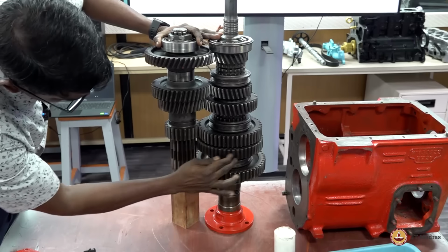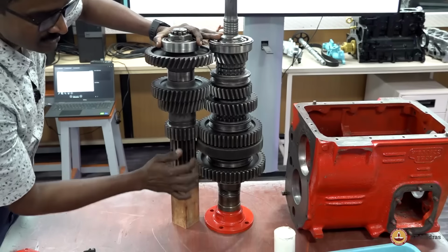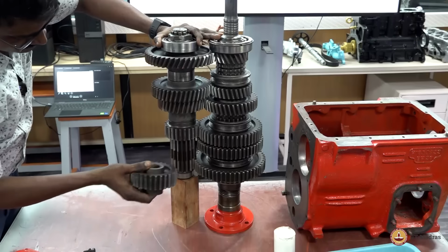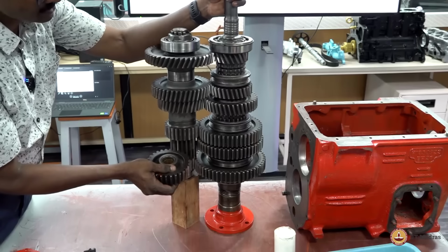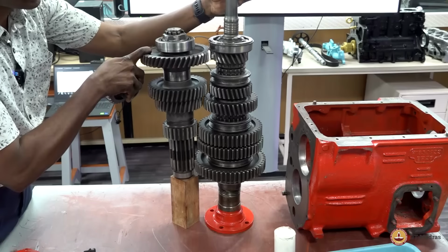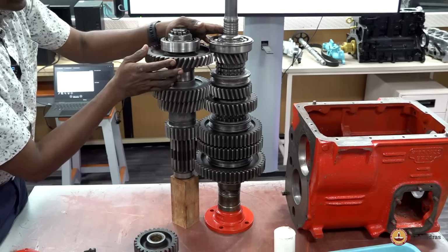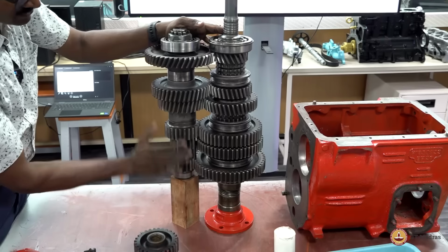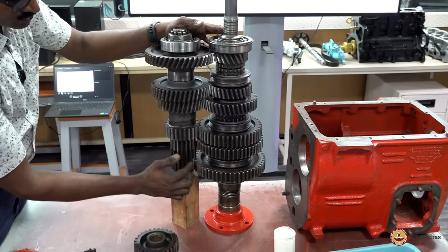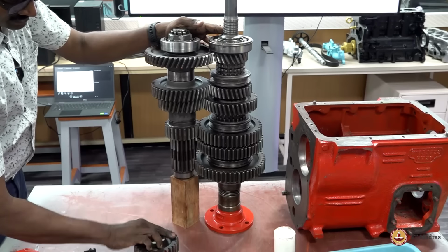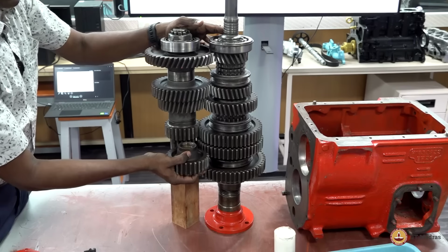As you see, there is no connection between the counter shaft reverse gear and the main shaft reverse gear. This is where the reverse idler comes into the picture. So once again I repeat. The engine is rotating clockwise. Whenever two external gears are meshing, the gear rotates in the opposite direction. So the entire counter shaft is rotating counterclockwise, and all the main shaft gears are rotating once again in the clockwise direction. But through the reverse idler gear, it changes the gearbox direction in the reverse gear.